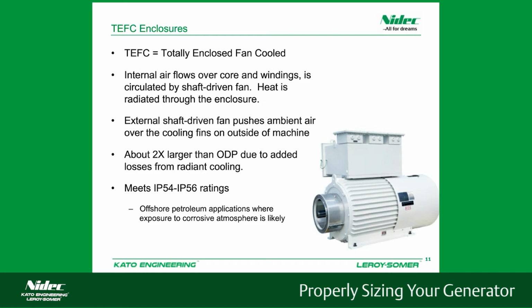The totally enclosed fan cooled is going to be about twice the size of an ODP due to the additional losses that we only see from the radiant cooling as opposed to having air moving through. Again, these will need an IP54 to IP56 rating. And you'll see these in offshore petroleum applications where we're exposed to a corrosive atmosphere.